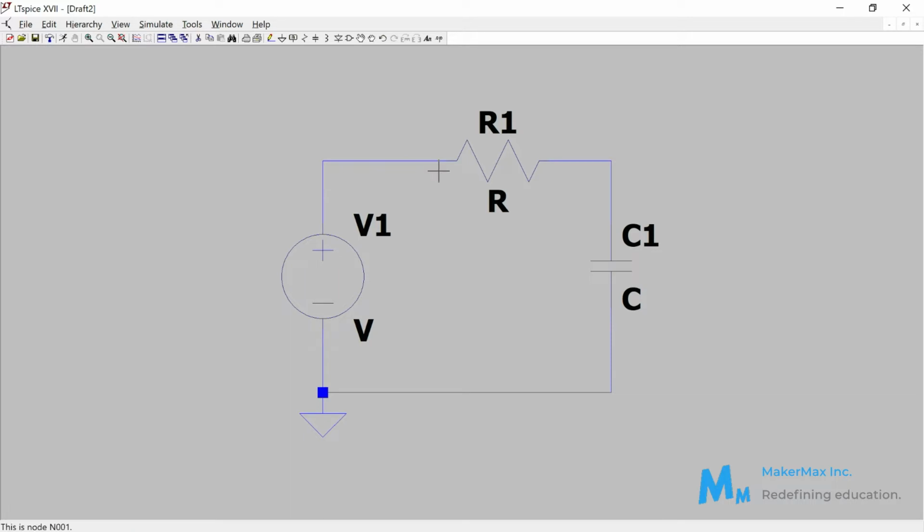And what would that mean? It just means that the capacitor will be charged to the same voltage as the source. So if the source is at 5 volts, the capacitor would already have a charge equal to a potential of 5 volts. So there would be nothing to see in the circuit.